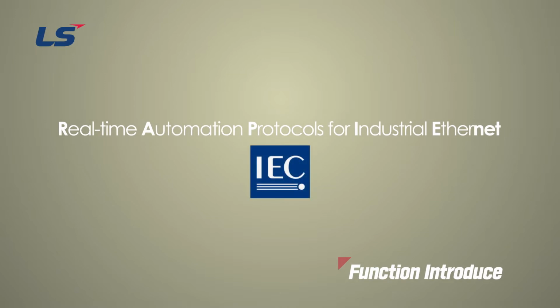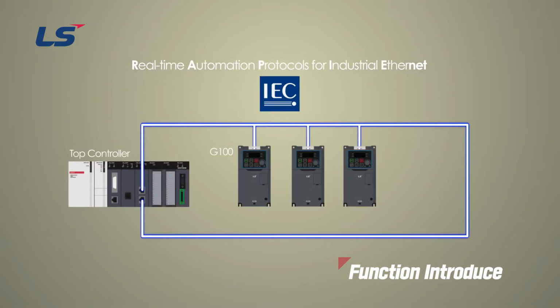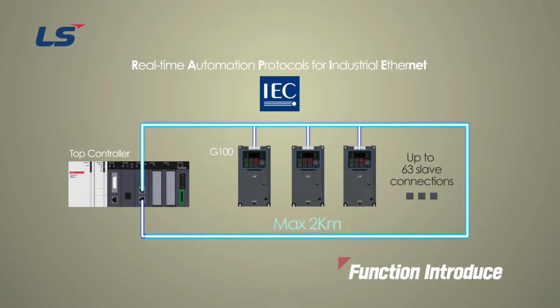The industrial switch function is built in to fundamentally improve problems such as lack of real-time performance, wiring problems, and lack of redundancy support function. In particular, the ring control function to support the duplication of communication lines supports the automatic selection of a ring manager without additional setting, and up to 63 slaves can be connected. In addition, data communication is possible up to a maximum of 2 kilometers between modules.